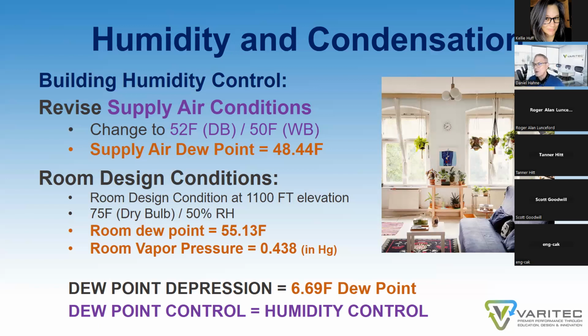And I'll never forget working with Judy Peters of Daikin when we did the 100% outside air variable refrigerant article for ES Magazine. When Judy evaluated a decoupled 100% outside air variable refrigerant system providing depressed dew point supply air on the outside air at 48 degrees dew point, she said, "Dan, wow, this is interesting. The variable refrigerant air handlers become predominantly sensible cooling devices only." This is an interesting concept, and we'll explore it further in future Webinar Wednesdays.